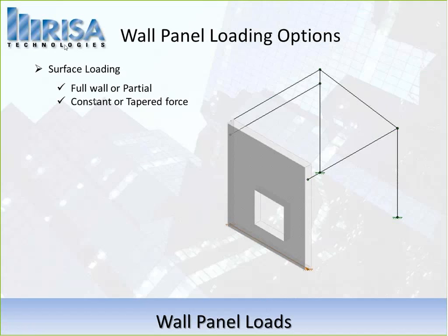You've got a lot of control on that surface loading, and we're going to see that. I'll demonstrate that in a second for you. You can also do distributed loads. Like I mentioned, you can do those to the edges of the walls, or maybe to the roof structure's framing, and we can put some distributed loads on there.